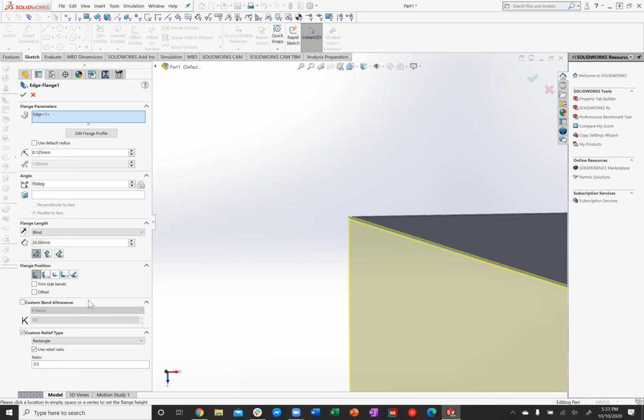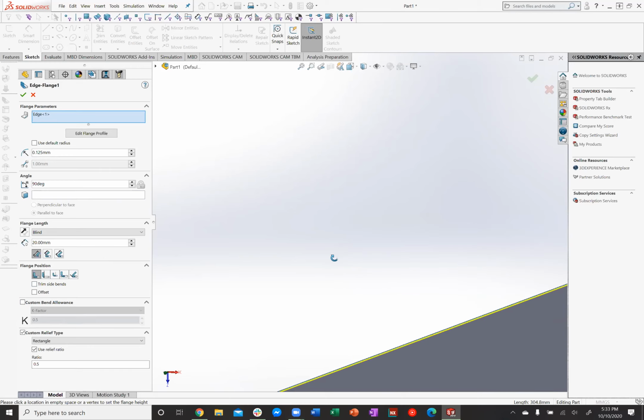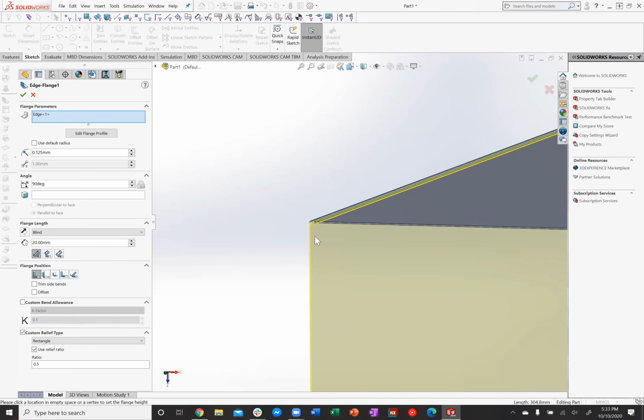The K factor here is something that we don't really use at school, just because we don't really know what it is for the manual. I don't even want to call it a brake press that we have in the shop. I call it a brake press. We'll just say that. But it's a box and pan brake. Okay. When you bend a material, it expands a little bit, and that is dependent on the thickness of the material and the bend radius and bend angle, and that gives you a K factor.